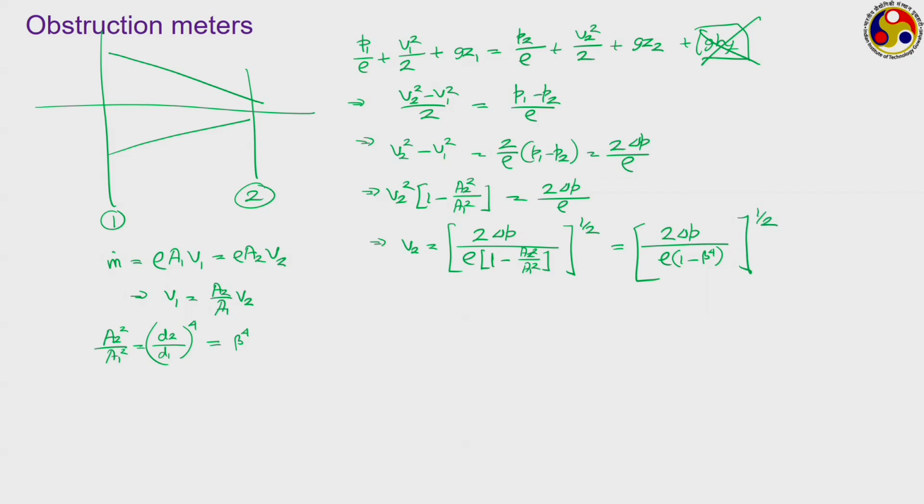However, the expression for velocity that we are getting here is the theoretical one. For this, what do we need to know? Generally, rho is the density of the fluid, which remains constant along the flow direction. Beta is geometrical information. So, once we know the dimensions of this channel, we can easily get the value of beta or beta to the power 4. The only thing we have to measure is this delta P, and we can do that using any common pressure measuring instrument, commonly a manometer. So, with that pressure measurement we can directly calculate this value of velocity.